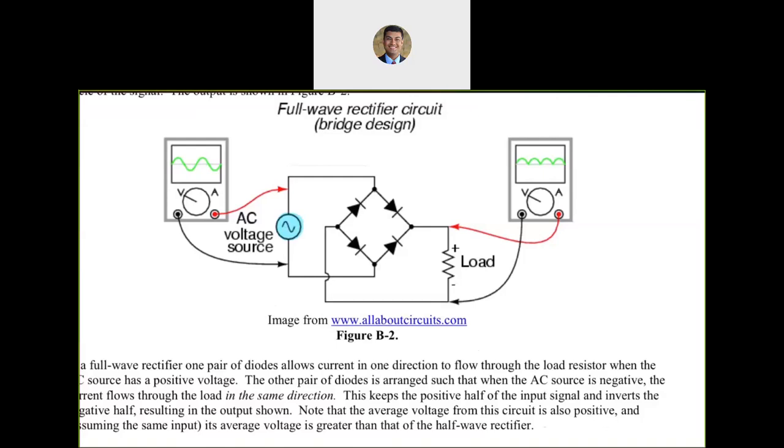So what is going to happen when there are positive voltages? So I'm looking at positive voltages in blue, and I'm going to trace it using a blue highlighter. Positive voltages, the current is going to flow in this direction, is going to come over here, and can only flow in one direction. Then it's going to go through the load.